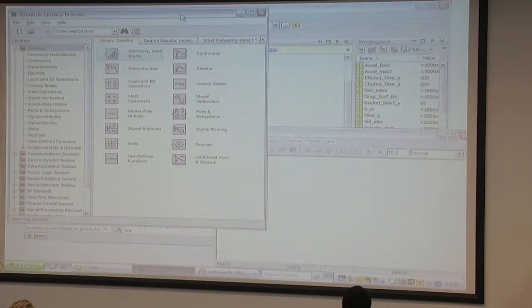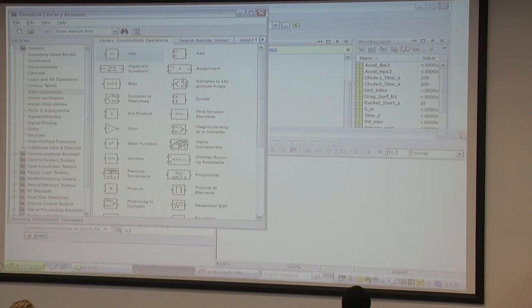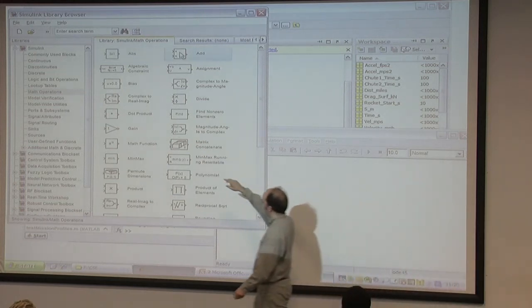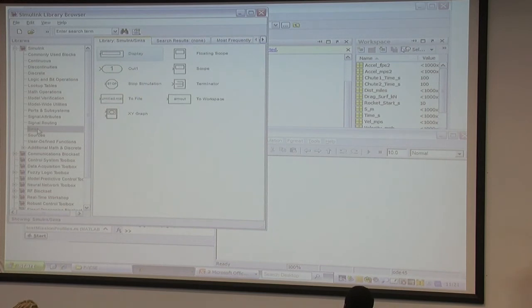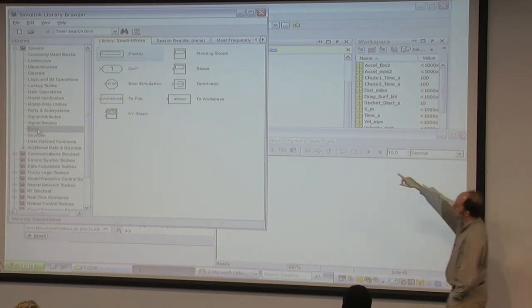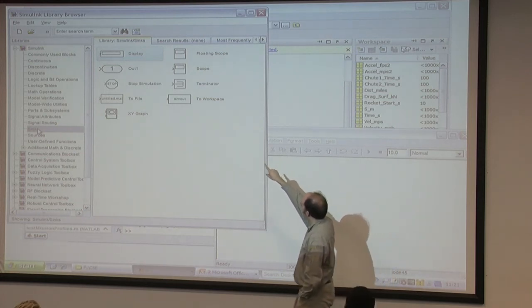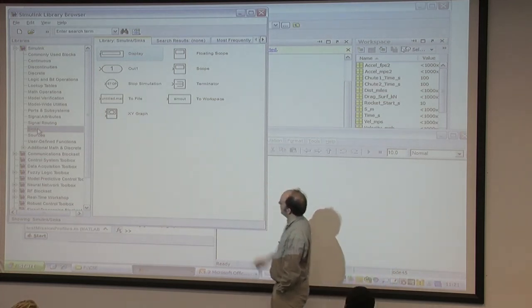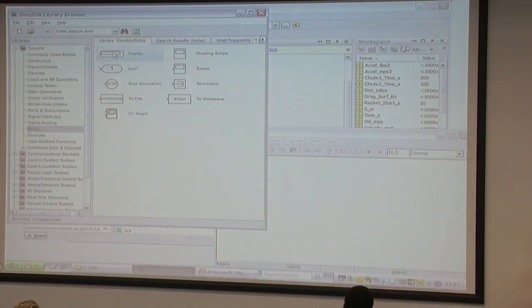Now in the library, there's various things that you can use. For example, I've got math operations. There's loads in here, but obviously that's a summing junction, add. I've got down here a gain I could use. So you've got product down here, okay, multiply things together. Sinks are where signals go to, so there's my scope, look, or my terminator, or like I said, to workspace as sim out, or to a file, saving as a MATLAB file, or I can display a number.